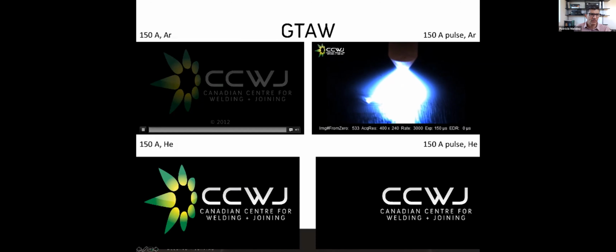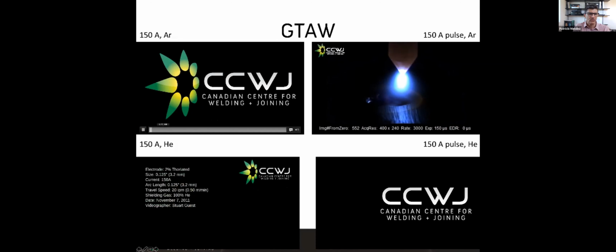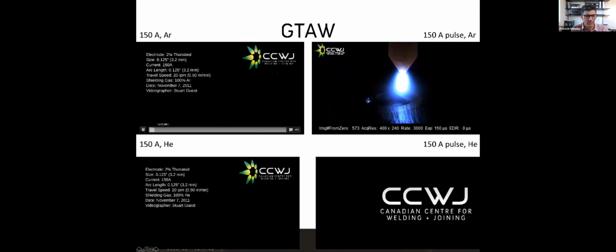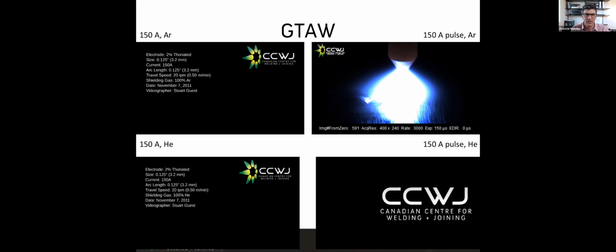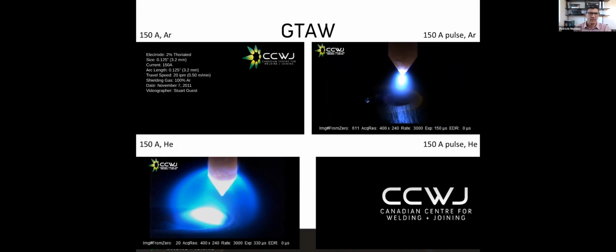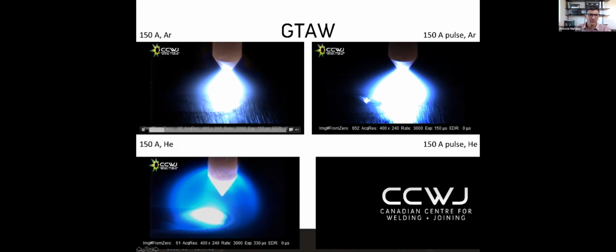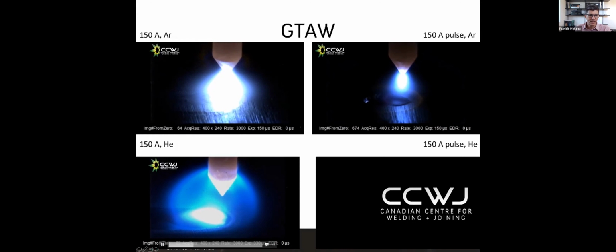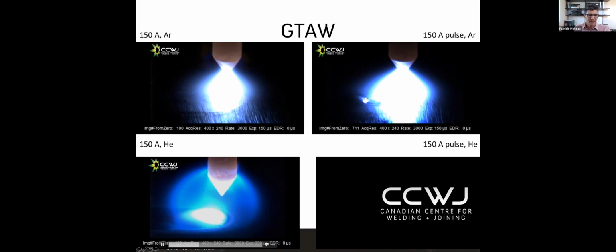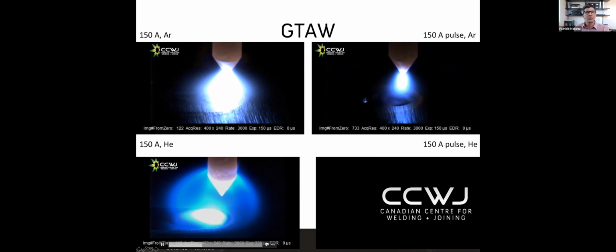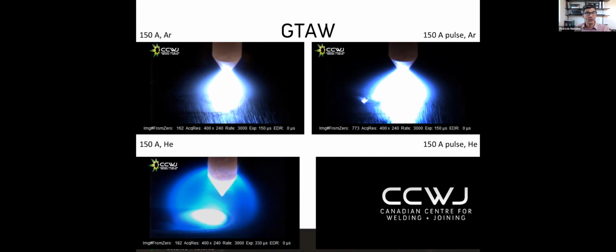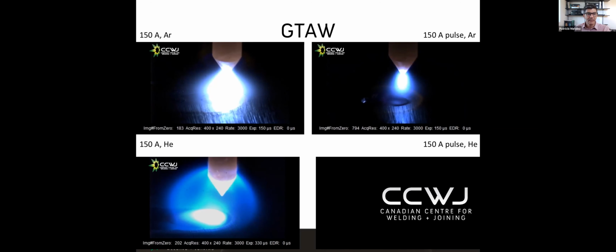And I'm gonna turn this on too, so you compare it with argon. It's a very different arc. You're gonna see it now. Look at this. Argon is kind of this concentrated arc, and helium is kind of this broad, ghostly arc. Isn't that interesting? When we talk about the physics of the arc, you're gonna see that helium also gives you a much higher voltage, much higher heat, right?